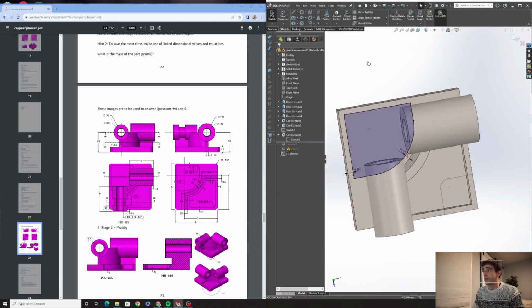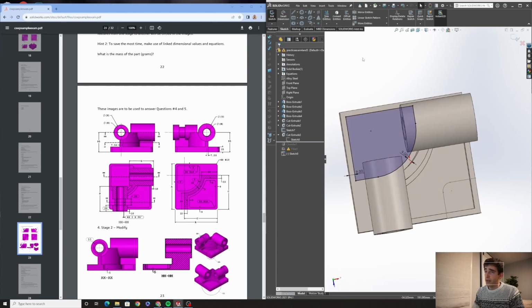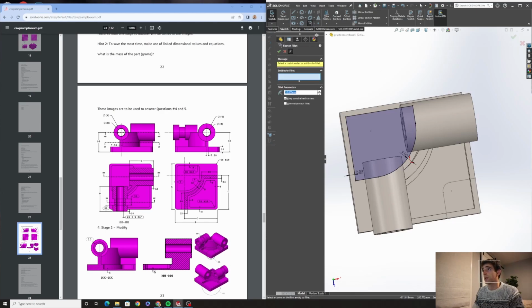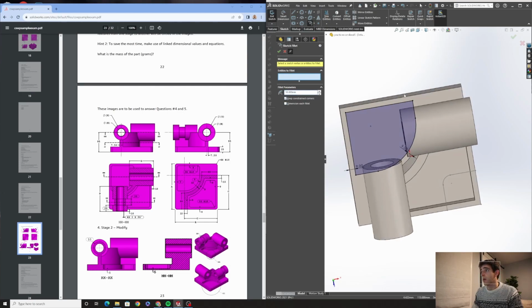trim these offsets. And so you can add your fillets either in as a feature or as a sketch. I mentioned that before. I want to briefly show sketch fillets. It's this feature here. It looks like we have radius 10. I can go into the sketch. I can create my fillets ahead of time.